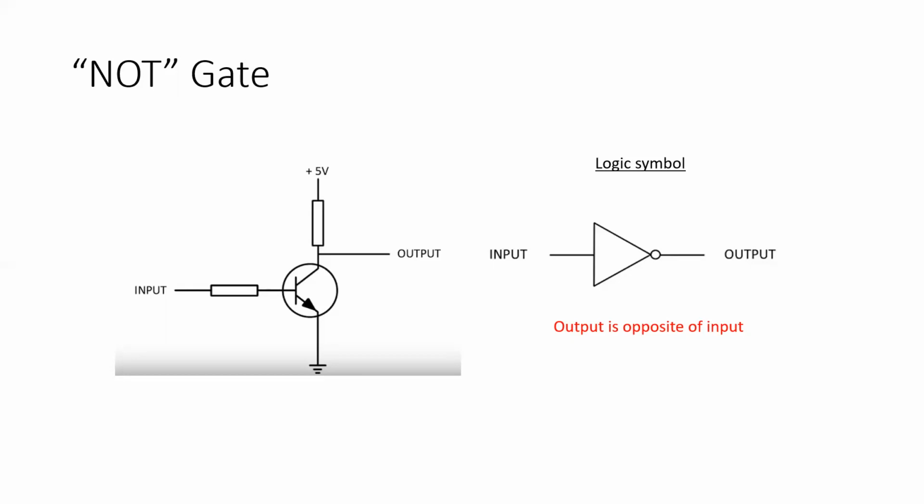Now, very often on an electronic circuit, we will only see the plus 5 volts of the source being applied, but not the negative. That's because on many electronic components, the negative is connected to the circuit board or the chassis, and that represents ground. So wherever we see a ground symbol on a circuit, we can take that to mean the negative side of the DC source.